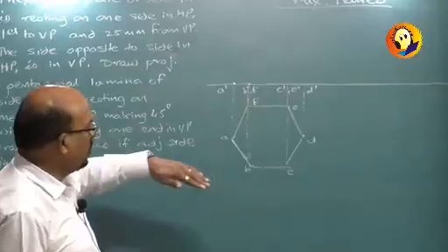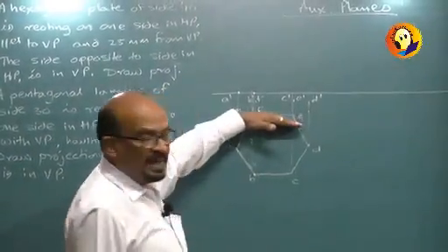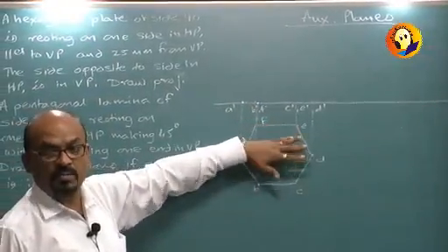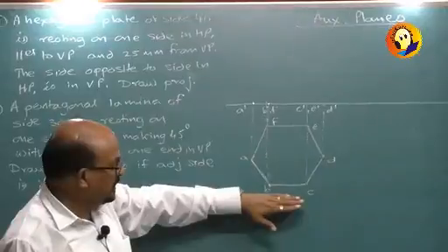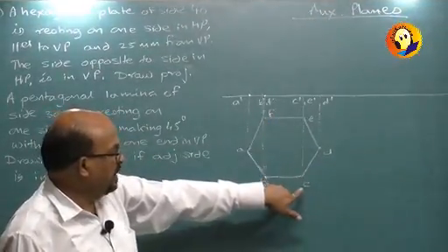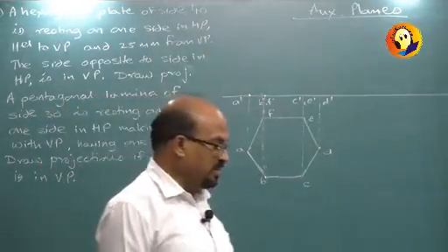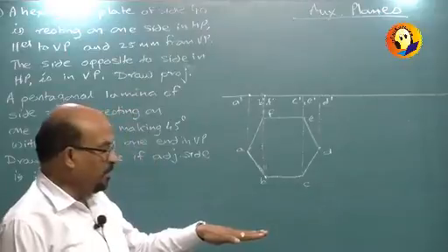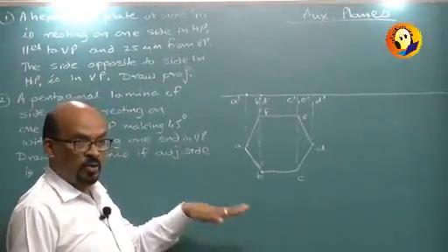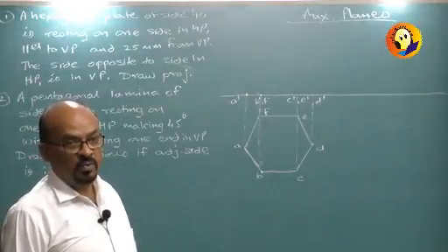Now the question is of rotation. This particular side should remain in HP and 20 mm from it, so we will have to rotate about it only. And this side BC, FE should remain in HP and BC should go to VP. Now this rotation, when it is trying to rotate keeping it parallel at fixed distance, and if I am to rotate it like this, the rotation cannot be seen in the front view, it has to be seen in the side view.